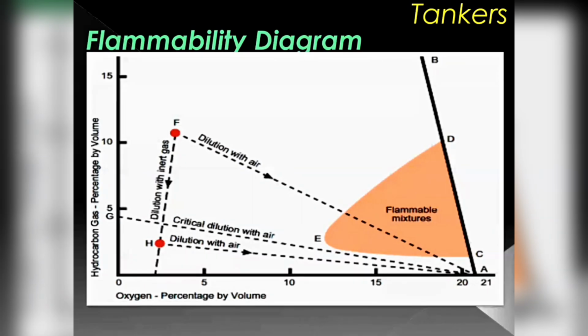Yes, sir. That's why they say you have to maintain a positive pressure inside the tank at all times, whether you are alongside or out at sea. That's why we are getting up in the night and topping up the cargo tanks with inert gas. Yes, sir. Because these three sides are available in surplus on tankers, and we cannot afford to have them meet each other to make a triangle.